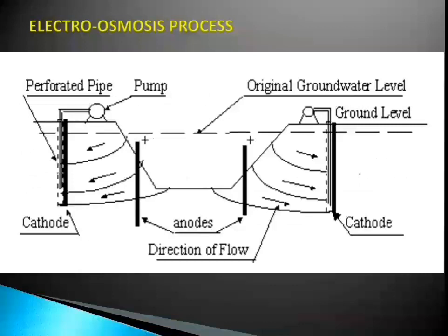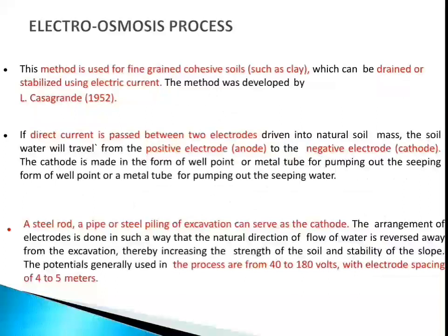Next one is the electro-osmosis process. We can see a schematic diagram of it. This method is used for fine-grained cohesive soil such as clay, which can be drained or stabilized using electric current. The method was developed by L. Casagrande in 1952.